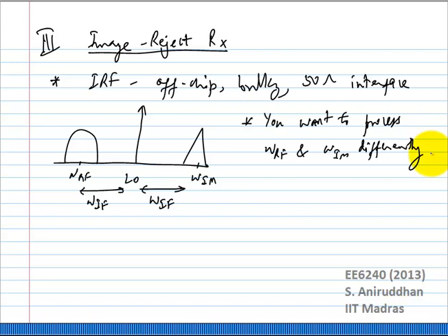So the idea is to make things easier, because things are not very high quality in CMOS. You cannot get very high Q filters, right? Traditionally you couldn't get a lot of amplification, but nowadays the devices are fast enough such that you can get a lot of amplification with less power. But really the thing to note is that compared to the amount of noise you are adding, especially downstream at baseband, flicker noise is still a big problem. Flicker noise and DC offsets are still huge problems in CMOS design if you compare it with bipolar design, for example.